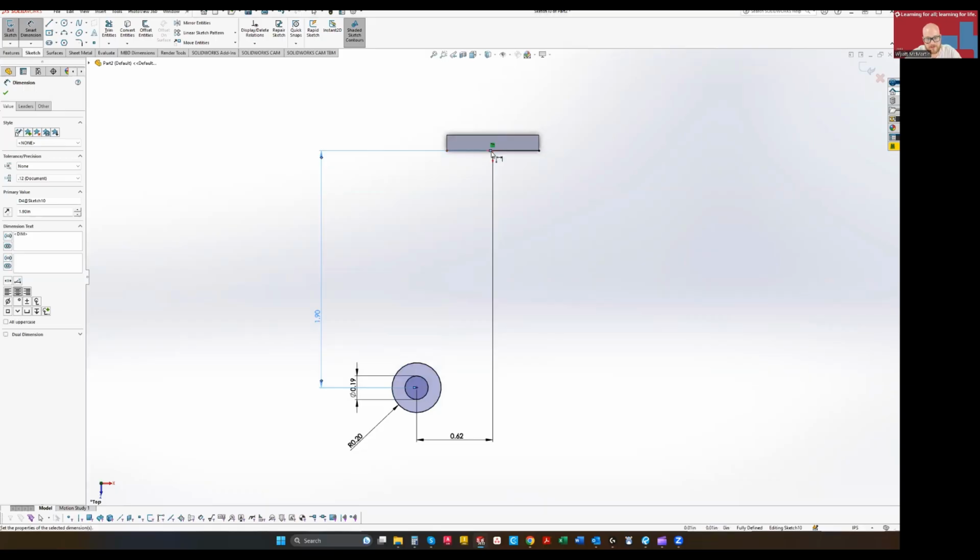Now, if you had chosen to extrude towards the front for some reason, instead of following me and extruding towards the back, you're going to have to adjust these values, or dimension from this front face, because the origin, if you extrude it towards the front, is going to be at the back of your part. So just keep that in mind, because when you dimension, if you do it incorrectly, the dimensions aren't going to work out for you when you plot this on the page.